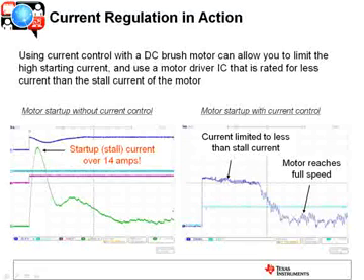But you don't want to have to design your power supply system to handle 14 amps, and you don't want to have to design your motor driver to handle 14 amps when the actual continuous current is much, much smaller. That's just overkill. So the solution there is the current regulation. And on the right-hand side, the blue line shows the current regulation in action, where it's limiting that inrush current at first. Once again the back EMF gets established, the current draw comes down, and you've got normal operation.